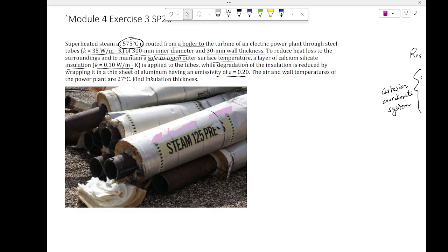Now, it's a design problem. You may argue, okay, I prefer 40 degrees. The problem with 40 degrees is, if you want to use 40 degrees as the outside design temperature, then the insulation will be that big, and you have to spend so much money. And there could be no point. Nobody normally touches a steel pipe with insulation, and it's an accident that may happen. So even with 50 degrees Celsius, maybe you are getting away with it without being sued, right? You know what I'm saying? Bottom line, it's a design problem. I'm just trying to give you the background insights. A 50 degree temperature is something that you can assume.